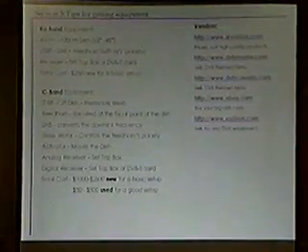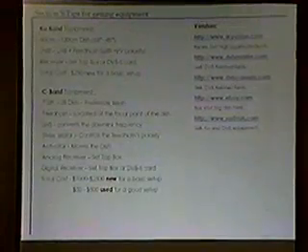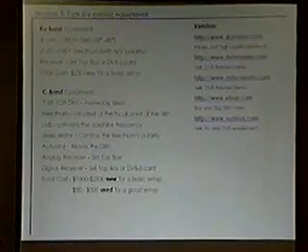The LNB, which converts the downlink frequency, these are all just the different parts. The skew motor controls the feed horn's polarity, and the actuator moves the dish. So the actuator was that device moving the dish as it went across. The skew motor knows when to switch back and forth. So if you have your receiver set up so that at this certain location, you want it to go to a vertical polarity because that's what the satellite is, then when you move the dish, it sends a signal to switch it to that polarity.